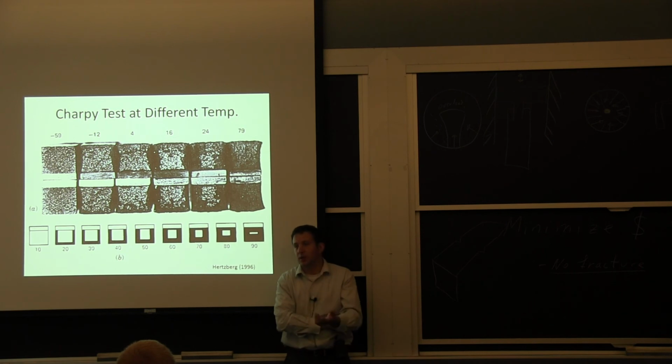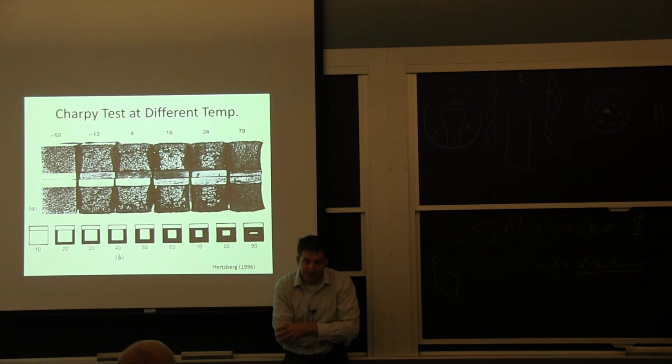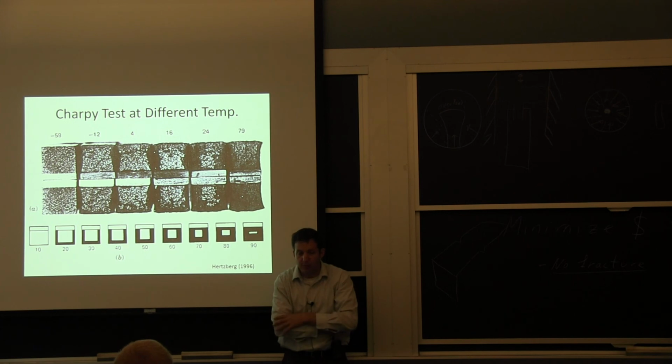If you really have a very low temperature application, you have to use austenitic stainless steel, so 304, 316, which is an FCC structure, so it doesn't have this increase in flow stress as you lower the temperature, or aluminum, for example. Now we talk about steel having this behavior, but titanium can have this behavior too. There are other materials that you have to worry about the effect of temperature.